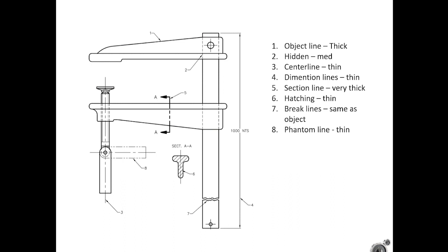You've probably seen the same thing happen on graphs at certain points when you're like, well, if we actually graphed this whole thing, there'd be 1,000 points of nothing and then some interesting stuff happening way off here. So we truncate the boring bit. We can do the same thing in AutoCAD. And this is an example of a break line. There's a couple different styles. And the break lines should be the same as the object being broken.